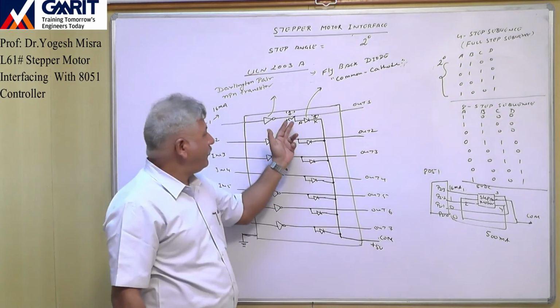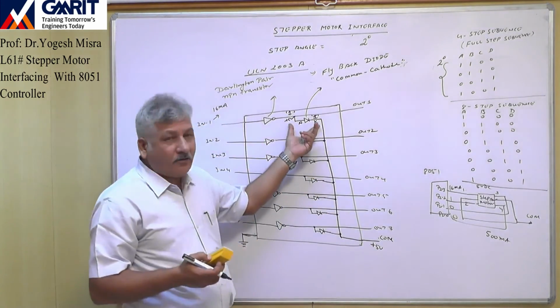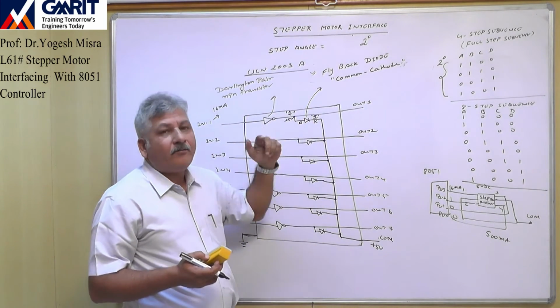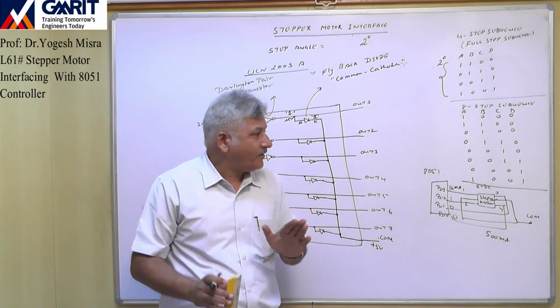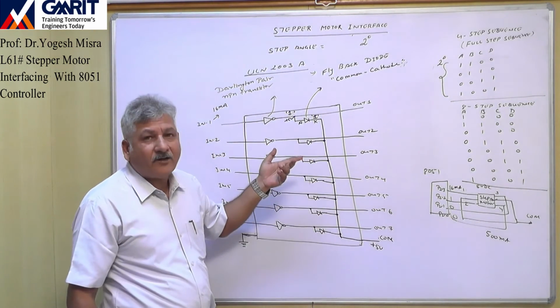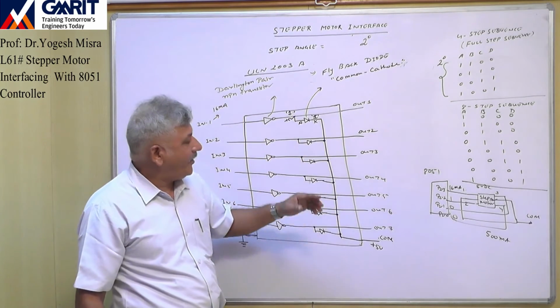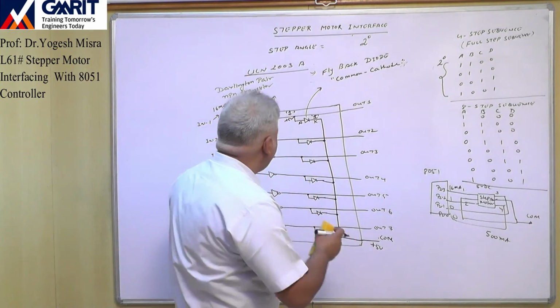So now both anode and cathode are at the same potential, so again this diode will not conduct. So whether this buffer is generating binary 0 or binary 1, under both conditions these flyback diodes will be in reverse bias condition. It will always be off. So in this way it will protect against the reverse current, right?